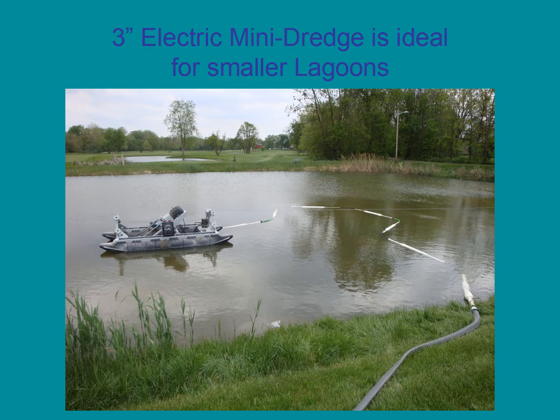A mini dredge can be used to pump sludge from the lagoon up to the bag area. This dredge is a cutter head style electric dredge and will pump up to 300 gallons per minute.